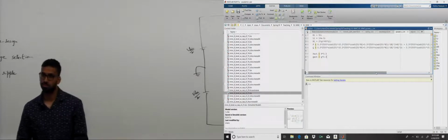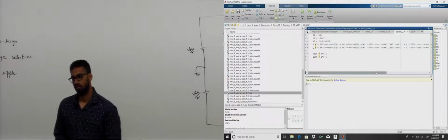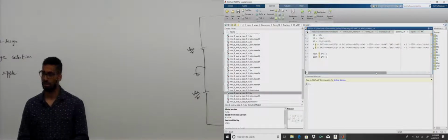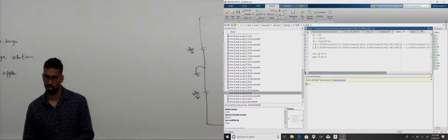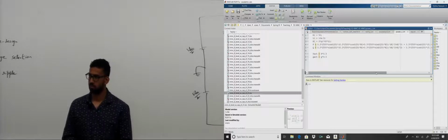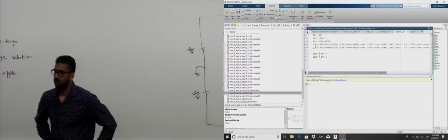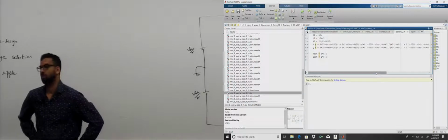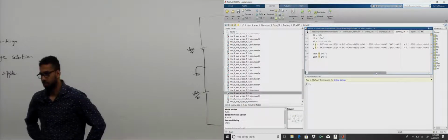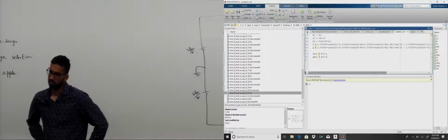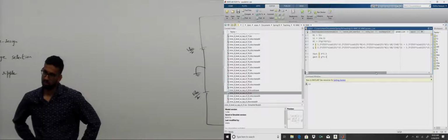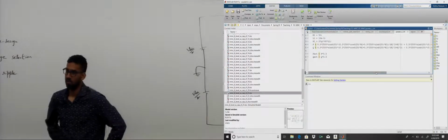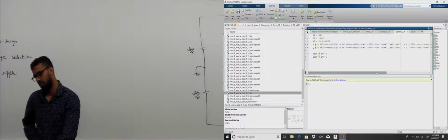What would you do if you were in a larger system and you had a fixed VDC and a given load? For that power, all you can do is reduce the modulation index, and the phase angle. What you produce at the output is in your hand, right? Because from this MMC, within limits, you can change the amplitude, and you can also change the phase angle at which that voltage is produced, such that for a given load, P and Q are simultaneously satisfied. Yes, we have 2 variables and 2 equations to solve. So M is a variable, alpha is a variable, and for solutions to these equations, the corresponding P and Q is possible.